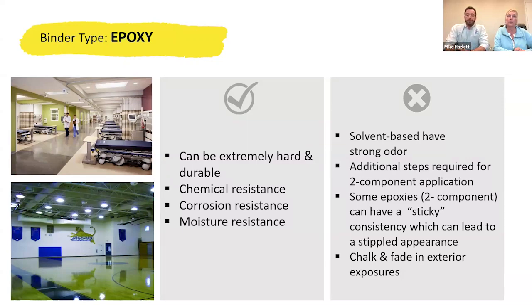Yeah, so you want somebody experienced with epoxy because they're very difficult to work with, and you have to follow the parameters that are on the data page for that. And epoxies, you will not see exterior. Yeah. We don't recommend it for exterior because they do fade. They will chalk up because of the ingredients within the epoxies. Yeah, and we'll have garages where the doors are open 6-8 hours a day, and after a while, several months even, you'll see almost where the frame of the sun in a door was causing chalking and fading, and then of course you're losing that integrity of the product.